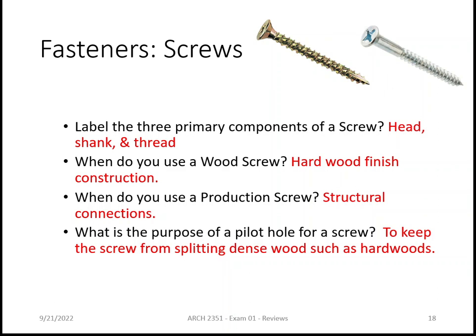What is the purpose of a pilot hole? Well, as it says up there, the purpose of a pilot hole is that you're going into hardwood. Hardwood has a very dense grain. If you don't drill a pilot hole, nine times out of ten you're going to split the wood. So it gives you a beginning, so that you won't split the wood, and just the thread of the screw will bite into the wood.